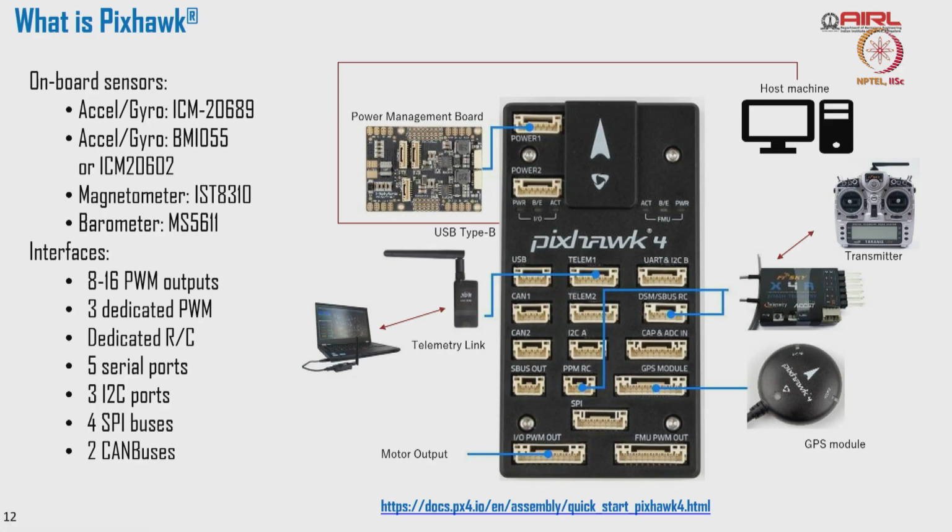Instead of using the decision making system, he can use direct control from a transmitter and directly connect and interface with the system. You can have a GPS module connected, which will give you the global coordinate system, your latitude, longitude, and I can fuse that information with my inertial navigation system and get my state.